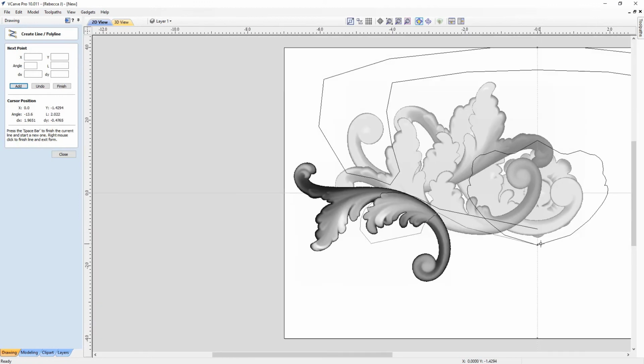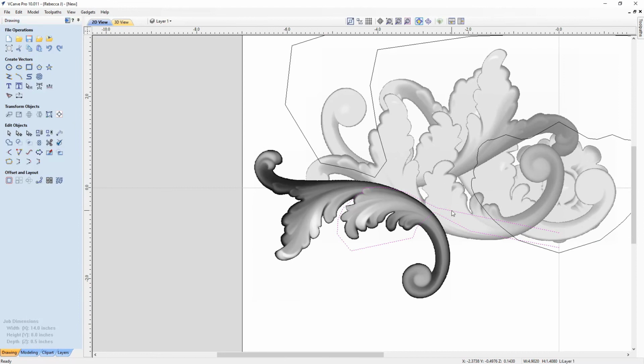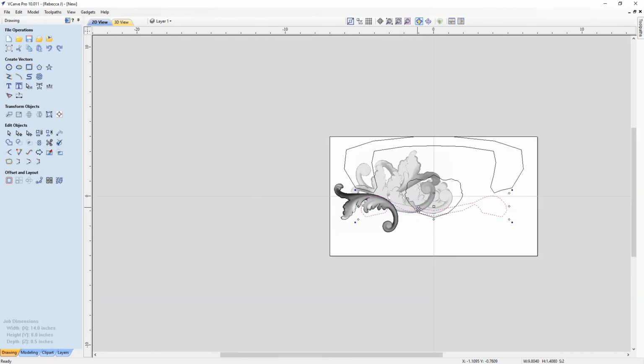And then again we need to come back over to the center there, and we'll just join those two vectors together using this join at the closest point. And then we're going to use Control Shift and H to create a copy over onto the right hand side like so, and then we're going to shift and select both of those where we can join them. Now we've got one joined vector.